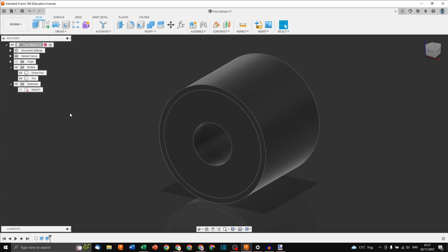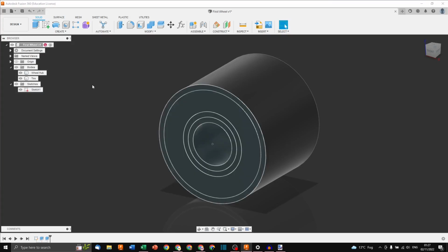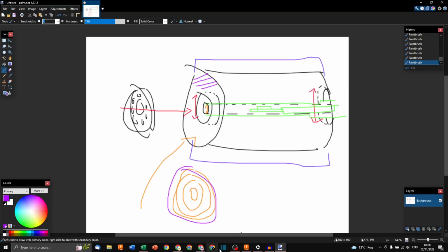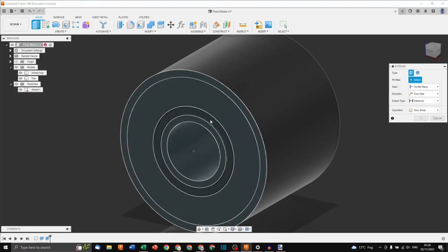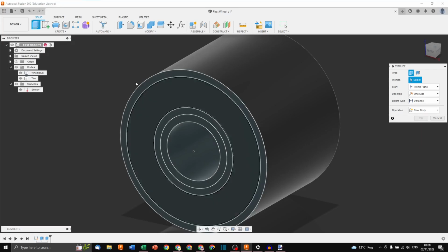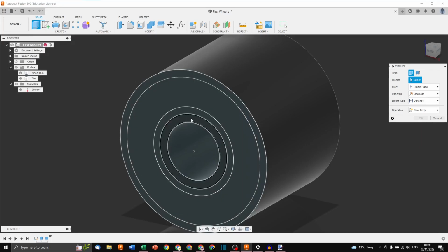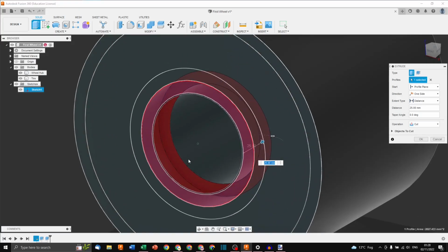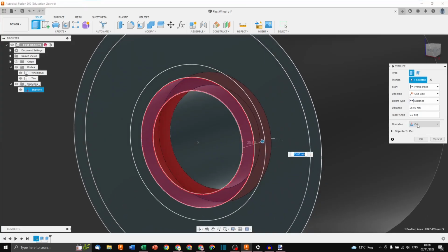That's great. Now, let's unhide our sketch once again, and let's extrude the bearing seats. The front of the wheel will be in the front of the model, so the front was the small one. Now I press extrude again, I'll choose this one, and I want to cut.